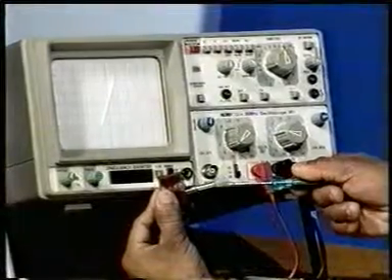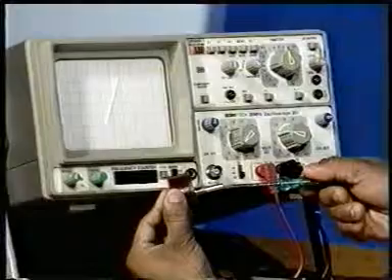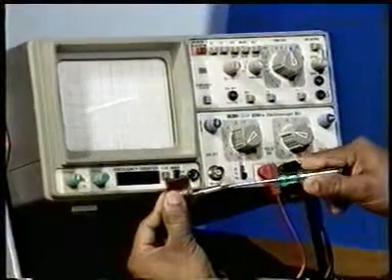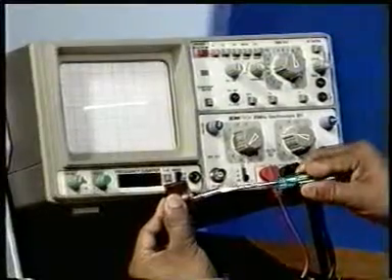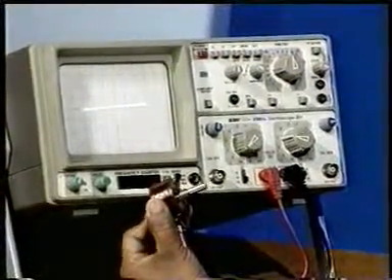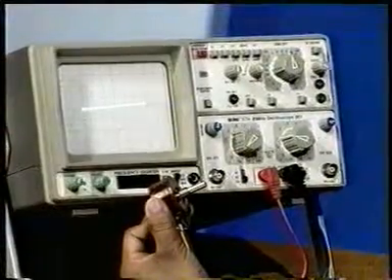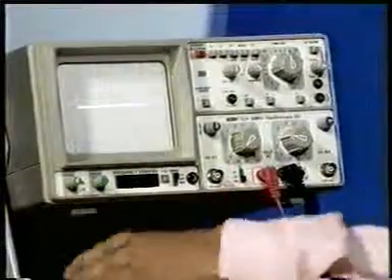What does it mean? It shows that the potentiometer is healthy, and it is going from its 0 value to its maximum value. Of course, this is an open sort of thing, that means it has the maximum value, and the vertical was almost 0, that is short. So the potentiometer shown here is a healthy one.